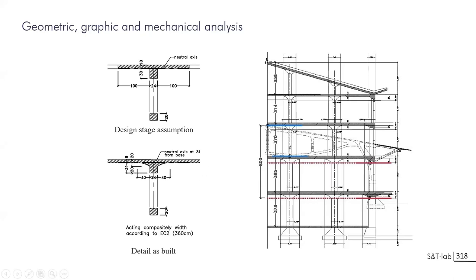You see that the top of the roof is just at the limit of the floor of the third floor. The lower part of the funicular will be just at the top of the lower floor. So these are the limits for the geometry. And we see that the dividing struts will be half of the span you have in between two columns. So you have a kind of graphical system in which you have to place yourself to design a structure.